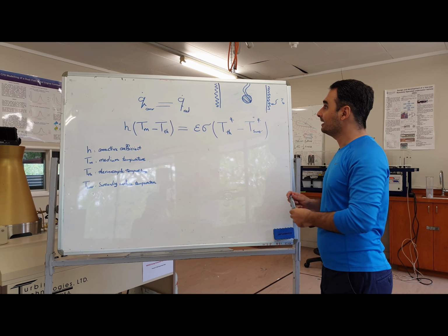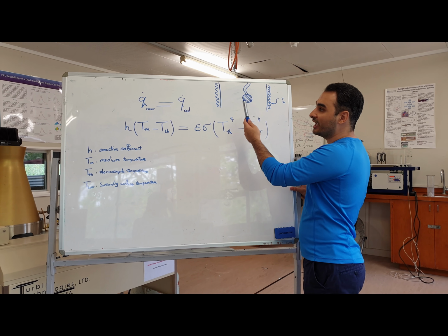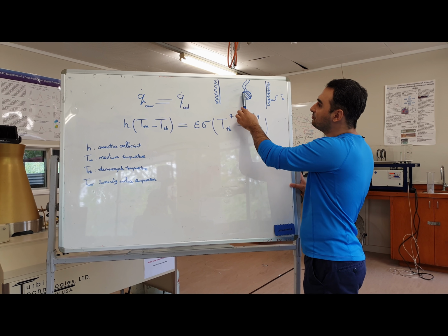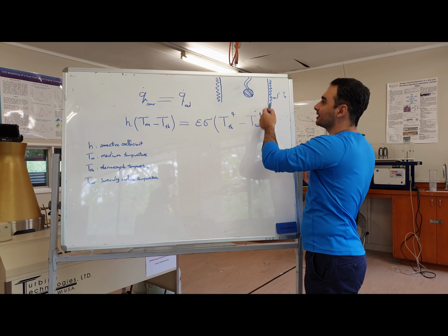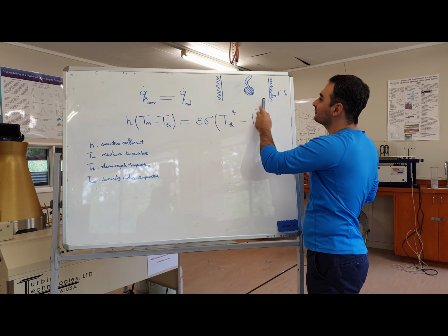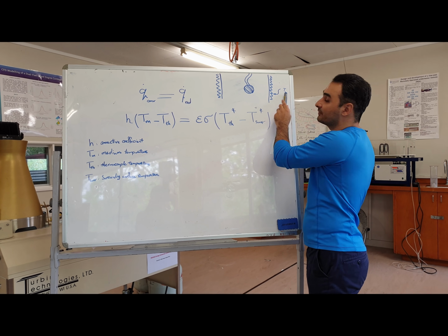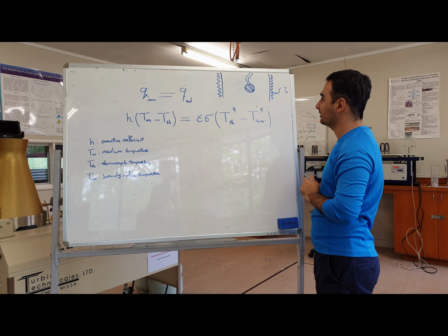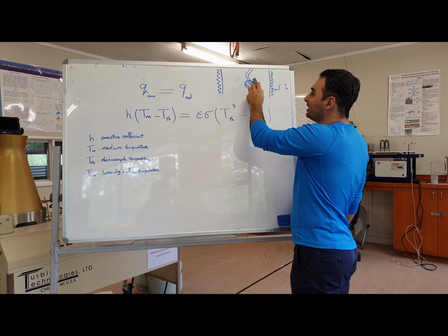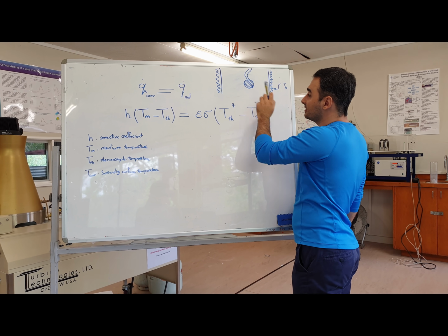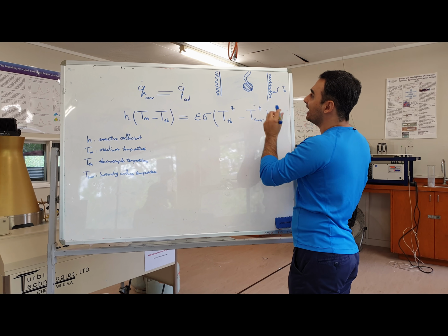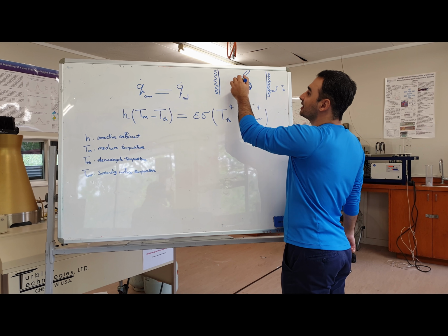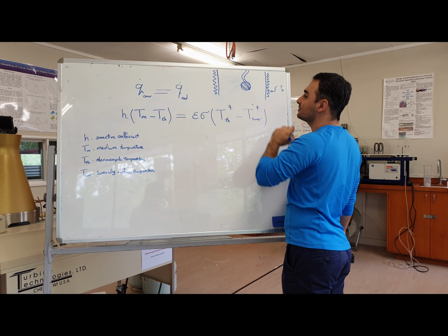Okay, let's see what we have here. We have this bit or tip of thermocouple inside the heated section, which we know what is the temperature of the heated section, which we can read using the T10 thermocouple. If our bit is a sphere, and for case number 4, we had both forced convection and radiation happening to this bit.